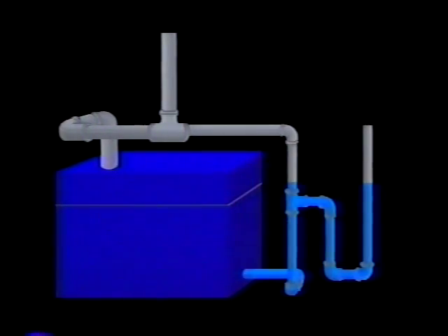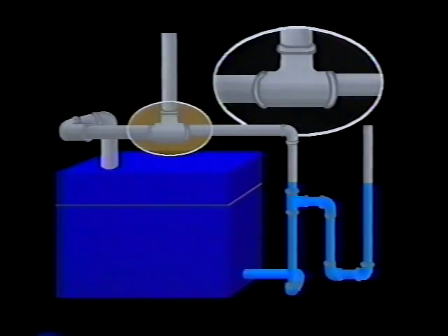Always reduce the header after the vertical drop into the equalizer. Never reduce in the header. This would result in a water trap without any place for the water to go.